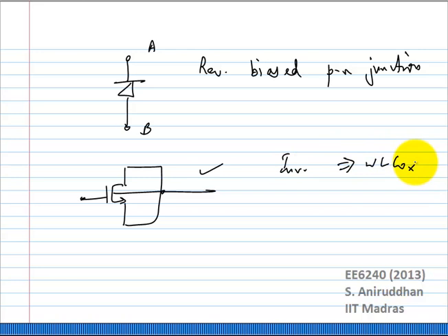If I keep reducing the voltage, obviously this will happen when the gate source voltage is very large, when the transistor is actually inverted. If I reduce it below Vt, what happens? Eventually, if I keep reducing it, the inversion region will not have formed, and I'll only have a depletion region, so only the depletion capacitance.